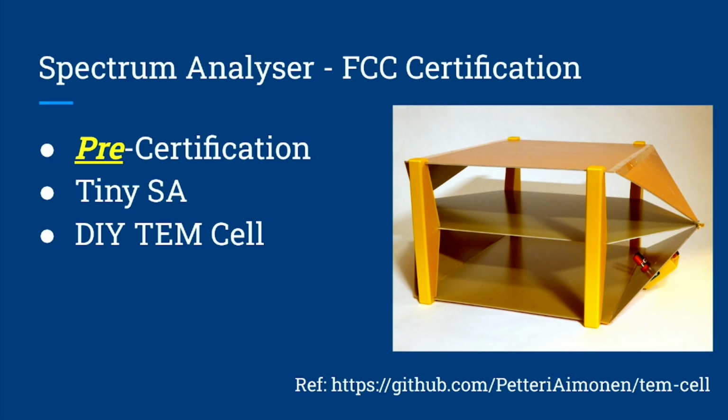And this is required because you basically don't want to send your device to a lab to get FCC certified if you're not fairly sure it's going to pass, because most labs will just charge you, whether you pass or not. We found one that has told us that they will let us retry, but it's not something that you want to keep getting wrong. So this is going to be my way of checking to see how bad our emissions are, hopefully not too bad.